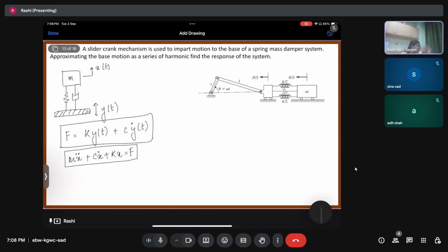We can convert that arbitrary forcing into any of these four kinds of forcing, and that advantage is given by the Fourier transform. That periodic arbitrary forcing can be converted into a sum of harmonics by the Fourier transform. Now, for every harmonic forcing we can find the solution, and by using the superposition rule we can just sum it up.